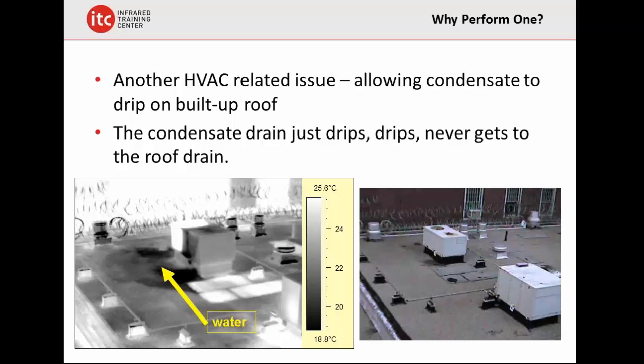Well, if you have warm clouds, you don't radiate that much heat. If you have a cold sky, you radiate a lot. And it depends on the roof. We need to get the excess heat off the roof. If you radiate too fast, your roof window is very, very short. In the case of a heavily ballasted roof, we want that. In the case of something like black EPDM, we want to stretch that out. You cannot predict this. So you have to tell your client, based on the roof type, I need several days maybe to find the ideal conditions to complete your roof scan.